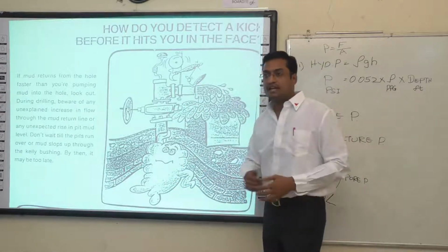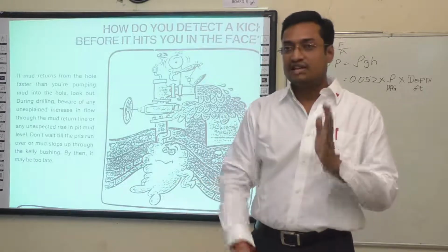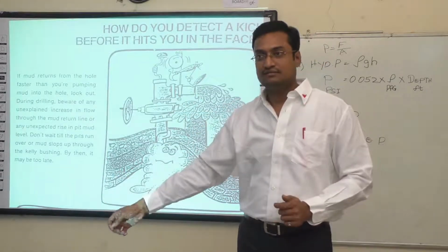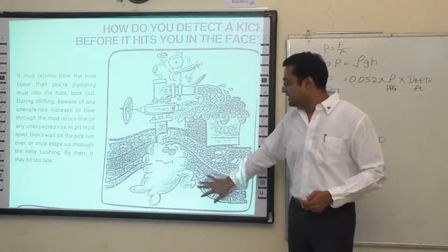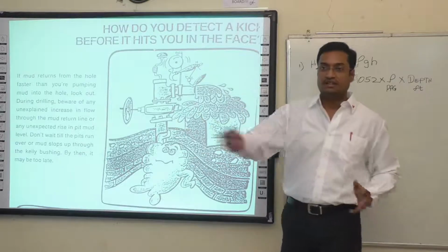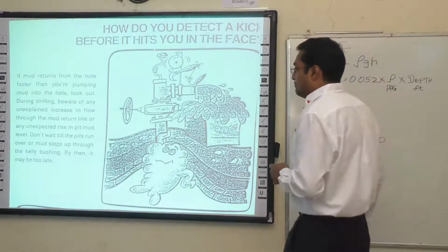But if you are getting 280 gallons of drilling fluid, that means there is some pressure difference. The flow rate is higher. You are pumping 250, you are getting 280. That means something else is happening downward, which is pushing out more fluids. That is the indication.